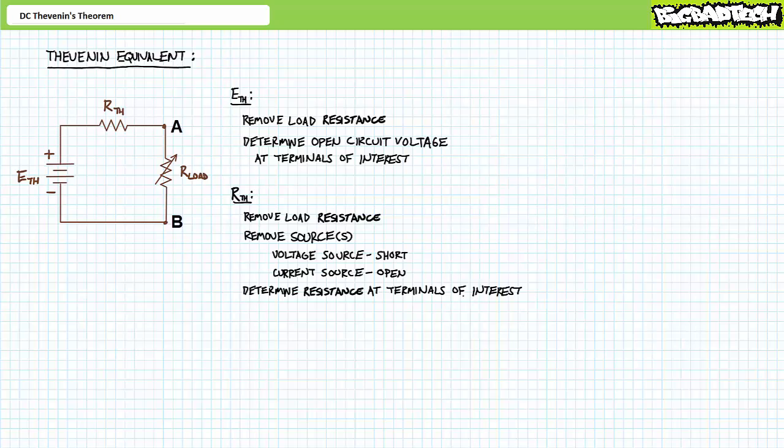Before we even begin discussing procedures, let me make something absolutely clear. It's all about perspective, and sometimes shifts in perspective mean different things. You can solve for ETH or RTH first. Order doesn't matter. However, you simply must understand ETH and RTH have nothing to do with each other and are never, ever used to solve for each other.